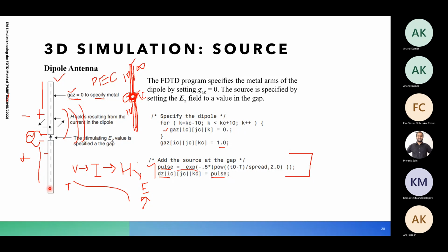And these electric fields will then propagate, like an antenna propagates the E fields. So once we give a source over here, all the E fields will be updated, considering it as metal, and then all the points around these nodes will be updated, considering that this metal is acting at the same potential given by this source over here.